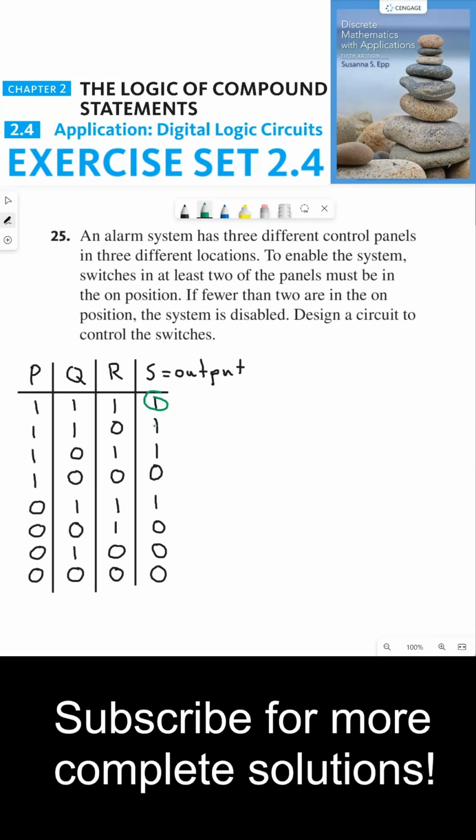Either P, Q, and R have to all be true, or P and Q have to be true and R false, or P and R have to be true and Q has to be false, or Q and R have to be true and P false. So either P, Q, and R all have an input signal of 1, or P is 1, Q is 1, and R is 0, or P is 1, Q is 0, and R is 1, or P is 0, Q is 1, and R is 1.